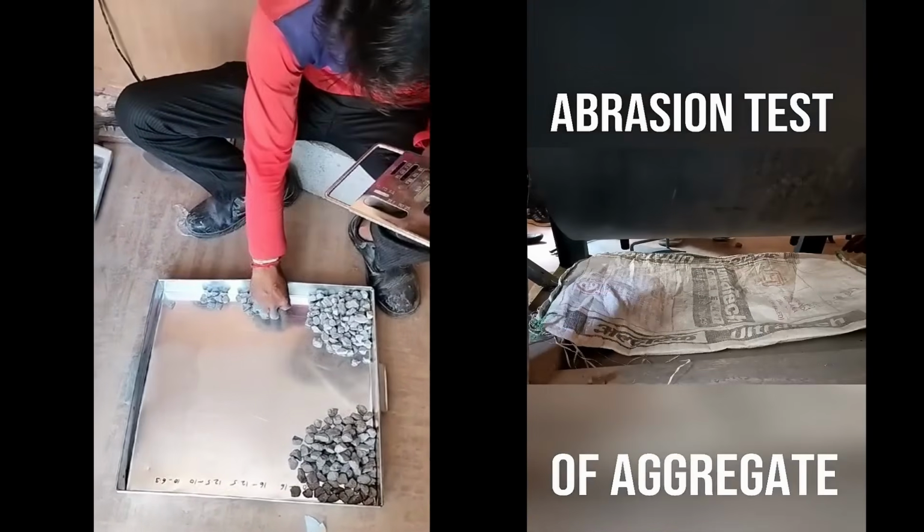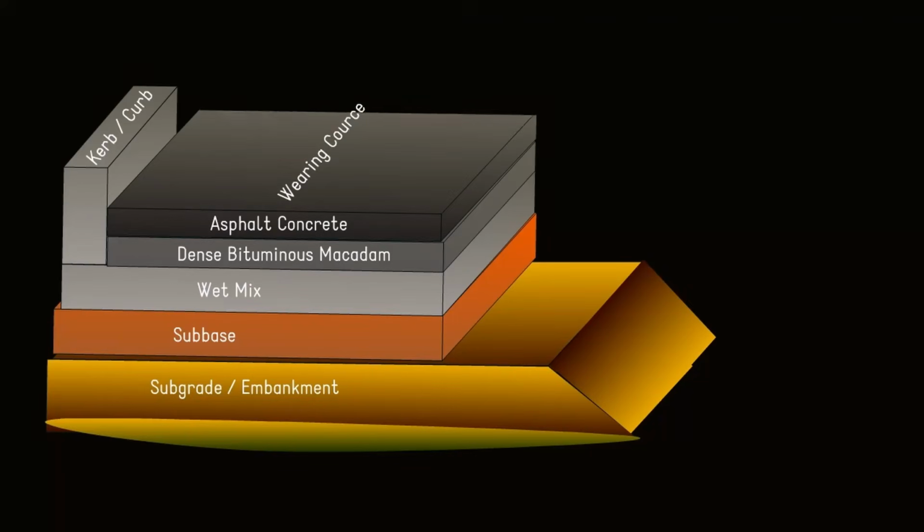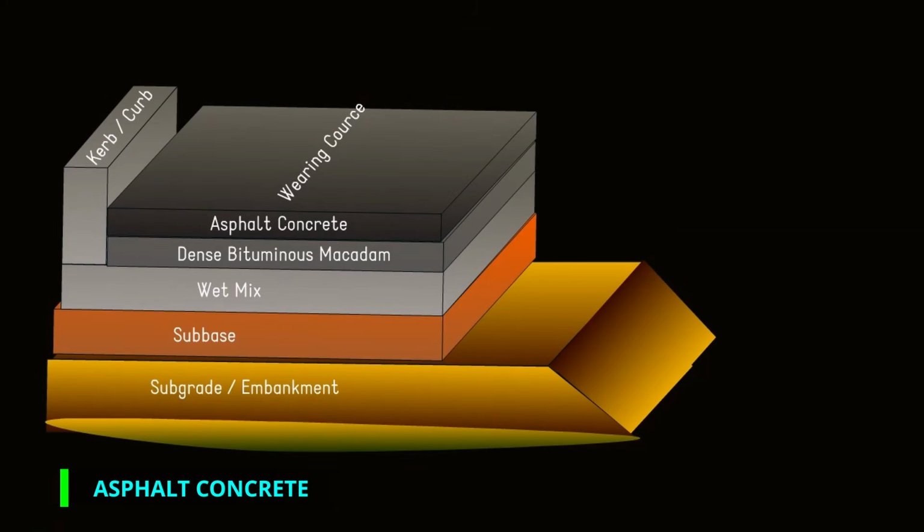The next item of work is the wearing course, also known as asphalt concrete. Asphalt concrete or wearing course. The wearing course is the final and finishing layer of asphalt work. The material selection and construction procedure are similar to dense bituminous macadam. However, the difference between DBM and the wearing course is the grading of the mixed aggregates.